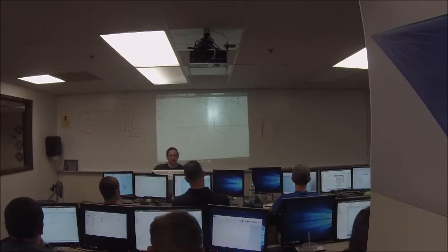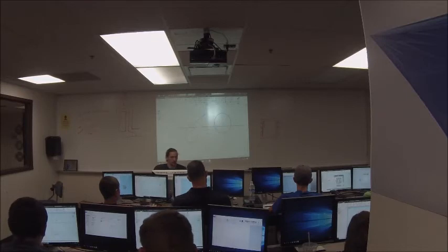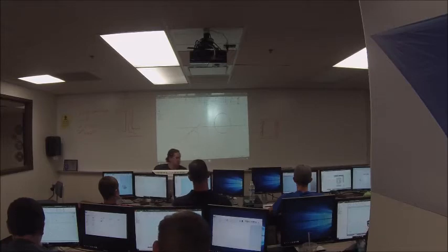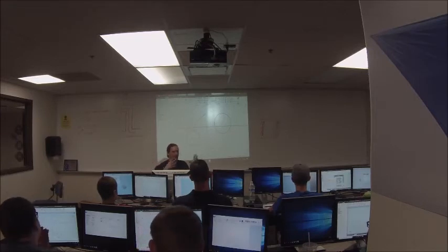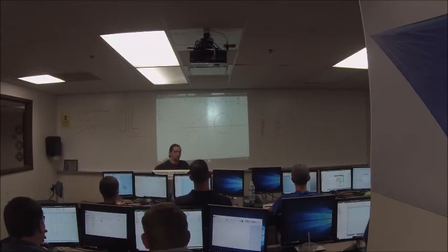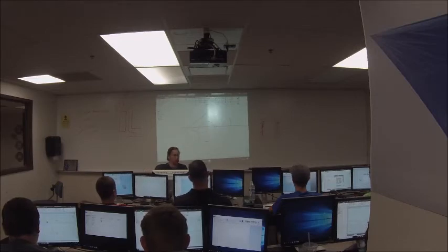So the tangent constraint allows you to make a line tangent to a circle. And you'll notice I can still slide the line back and forth, right? But it stays touching the circle. Okay? Now it also works for two circles. Pretty much anything you can do to a circle, you can also do to an arc. So I'm kind of just generalizing when I say circle, but it also applies to arcs. Arcs are just sections of circles, right? So you can make two circles tangent, right? And then they touch at one and only 1 point.